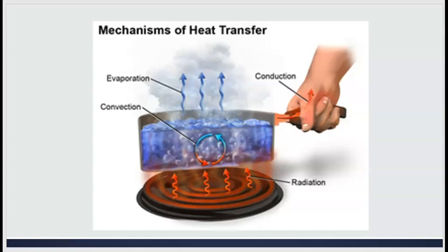So where you place the air in a building, depending if you're heating and cooling, depends on what temperatures you're looking to get the space and what the room temperature is prior to that. A lot of times this is why we put the intakes lower into the room and the outtakes higher on the ceiling. That way hot air rises out and leaves the building, leaving the cooler air behind when we're trying to cool a space. The other thing is evaporation.